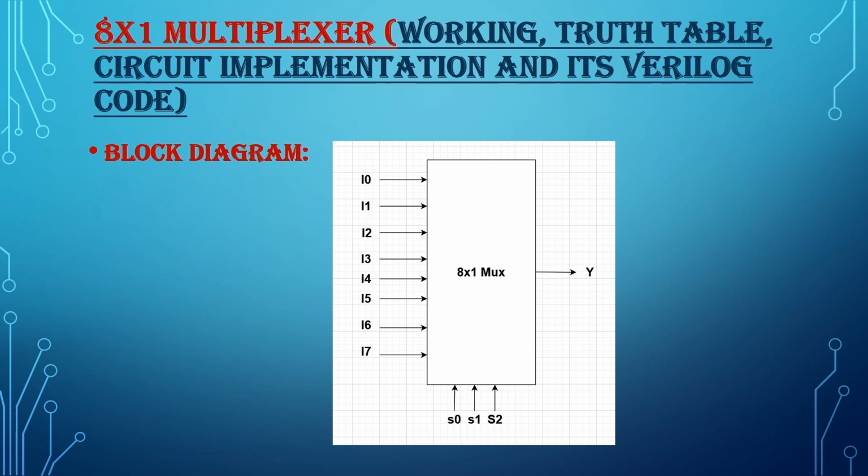So the 8x1 multiplexer, which we can simply call a MUX, is a combinational logic circuit that selects one of several input signals and forwards it to a single output. And this is a block diagram of the 8x1 multiplexer, where I0 to I7 are called input lines, S0, S1, S2 are called selection lines, and it has only one single output, that is Y.